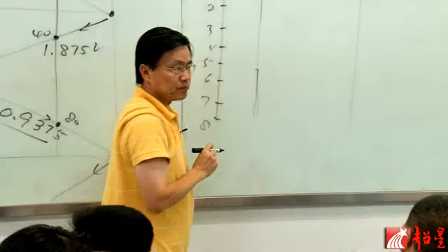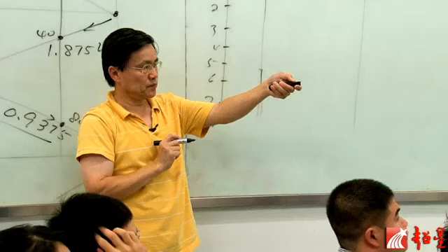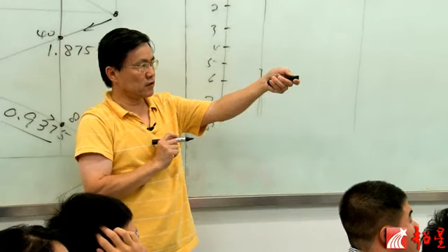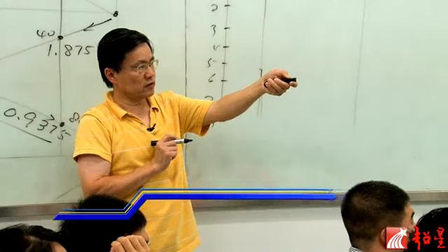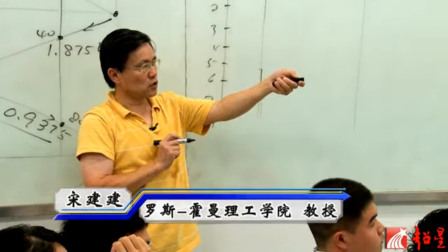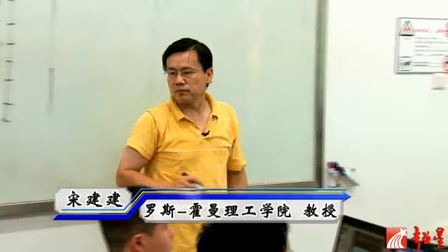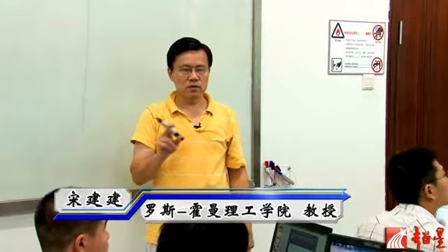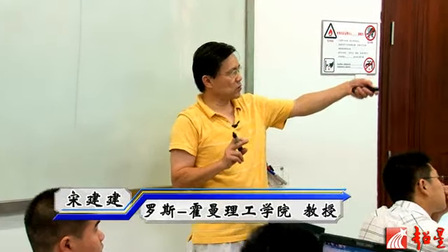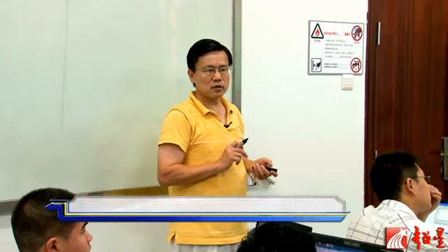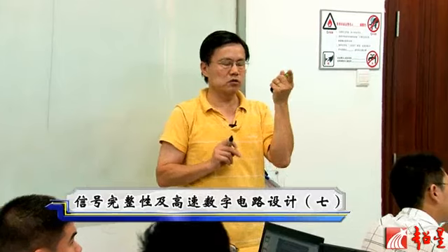Now what's going to happen? What's the reflection coefficient at this point? This is 50 ohm. It's going to hit this branch here. There's a 50 ohm there, the 50 ohm here. So what does this wave see as a load? Say it again. 25 ohms. Because these two are in parallel. So this wave is going to see 25 ohms. So what is the reflection coefficient?